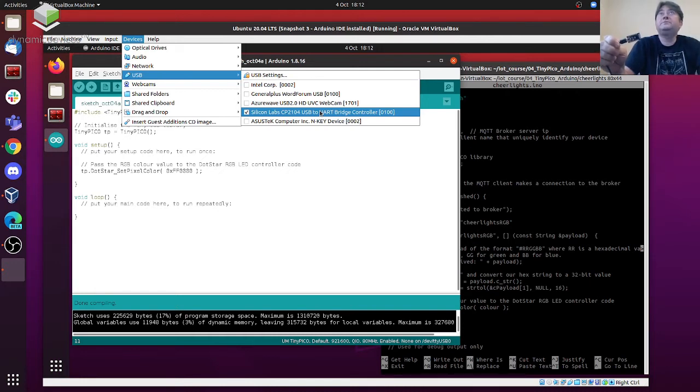There are different ones. That's what these people have chosen to use. And that really just sort of sits there and it moves things from USB into the chip over the serial backwards and forwards. And that just makes everything a lot easier than having to deal with serial connections, which are old school and can be a bit of a pain nowadays. So if you needed to, you would check that box to connect your device up to the virtual machine. And I go through all of this in one of the previous talks, so again, any confusion, just go and have a look at that.